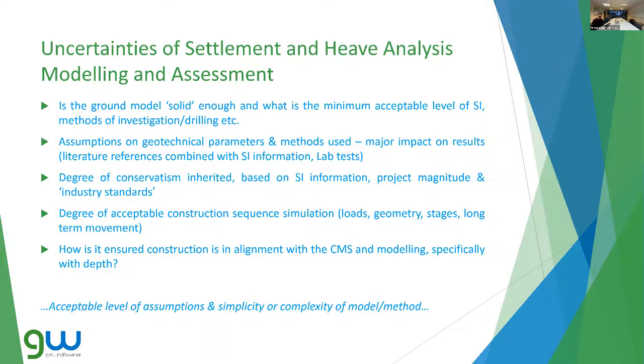So there are issues there, and then we also have to think about the geotechnical parameters and the methods that we use and how we derive this data. Do we use literature? Do we use SI information, lab tests? Normally it's a combination of all, but this doesn't mean it's completely perfect. And then there's also a degree of conservatism from your SI information based on industry standards and things like that. So that's another uncertainty and potential conservatism.